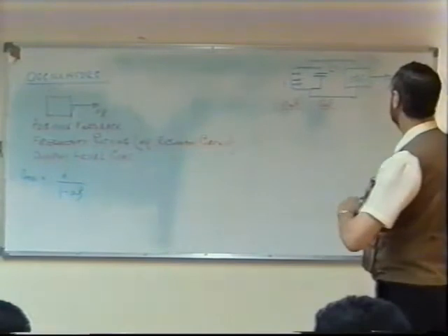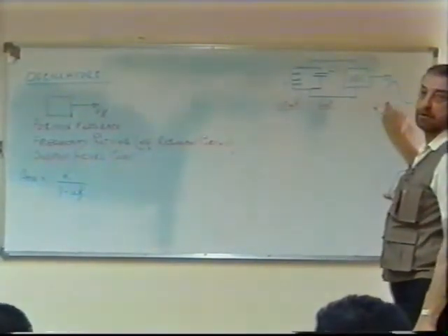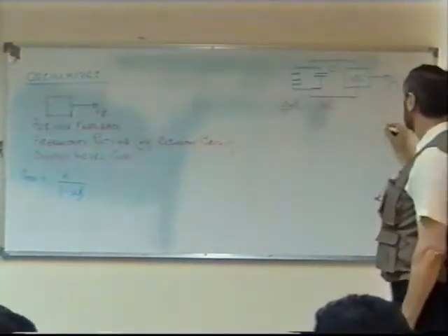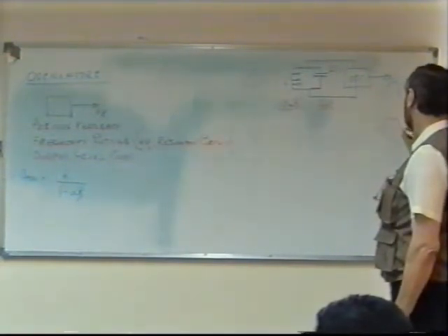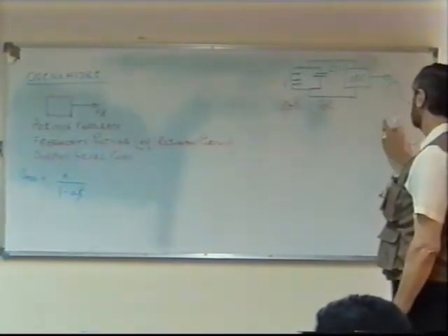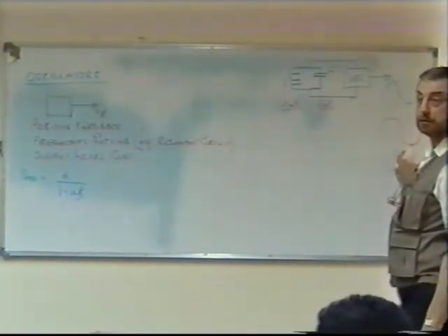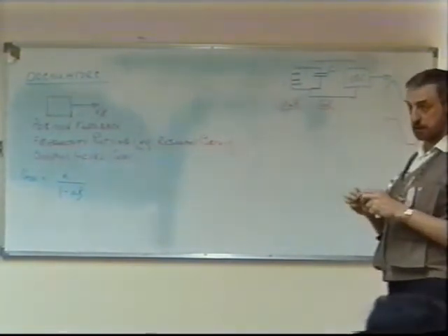The only time you generate harmonics is if your output signal is not a sine wave. For example, if we overdrive the oscillator, then what happens is we cut off, like that. Now this cutoff here will produce harmonics. But if we don't overdrive and we produce a sine wave, we won't produce any harmonics.